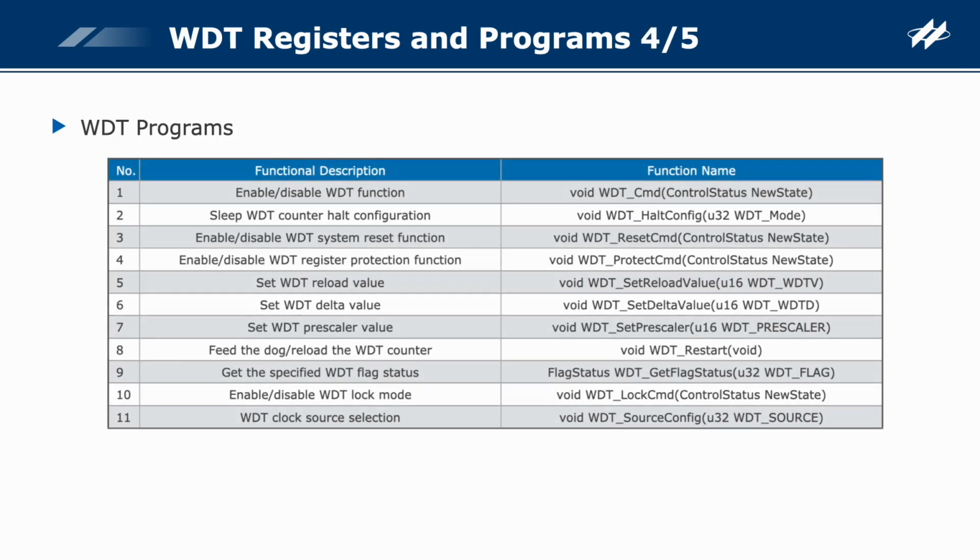The watchdog timer monitors the system status using the timer mechanism. If an abnormality is detected, the watchdog timer can respond quickly by executing a system reset, effectively preventing the system from crashing or entering an error state due to a fault. This improves the system stability and reliability.